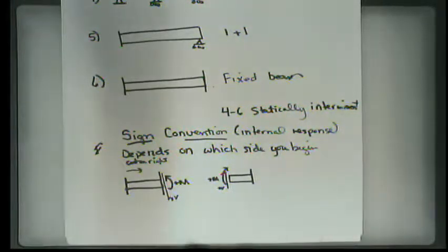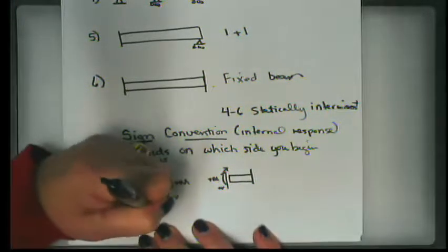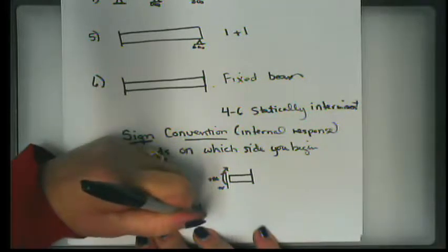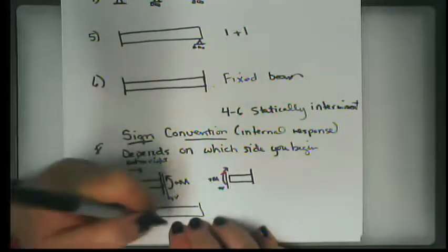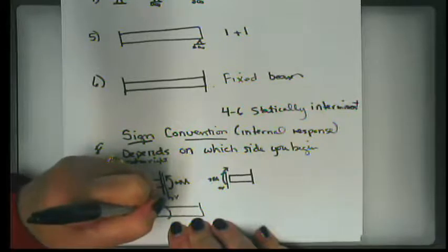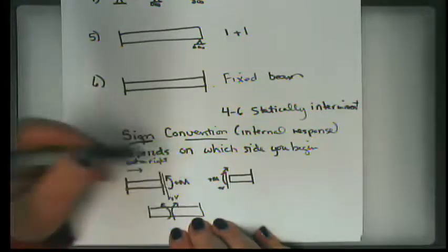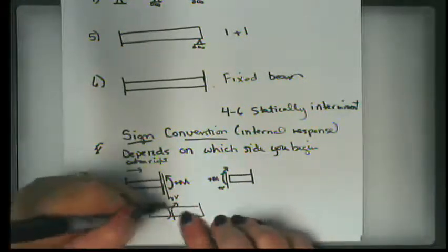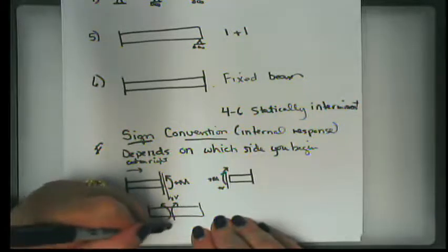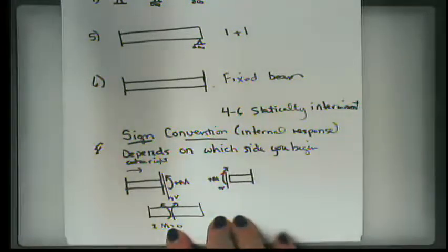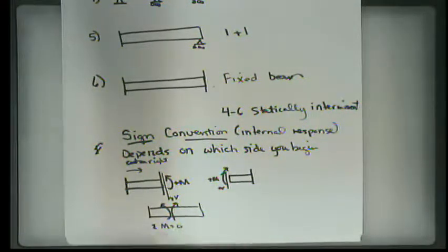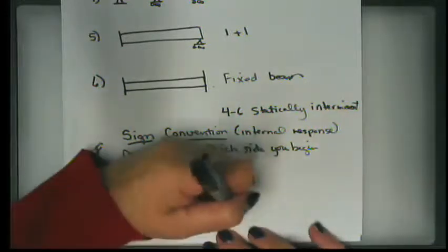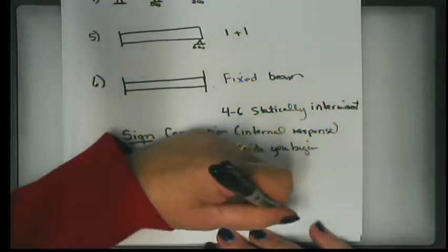Now, the reason that we do this is because if you think about the actual beam, at some surface, you have moments that oppose each other, so the net moment is equal to 0, which is required for this beam not to rotate. So everywhere you go, the moment has to be equal to 0 in sum everywhere. And the same for the shear.